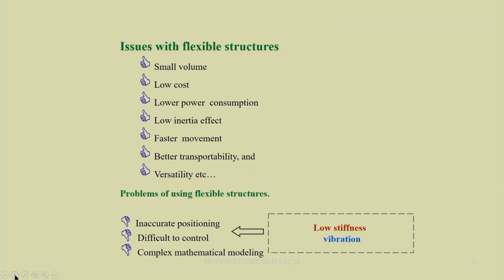But what are the issues with flexible structures? They have small volume, low cost, lower power consumption, low inertia effect, faster movement. So, better transportability and versatility and many other advantages are associated with flexible structures, but there is a large disadvantage. The problem with flexible structures will be inaccurate positioning, difficulty in control, and complex mathematical modeling because of the low stiffness. So, the system is subjected to vibration.